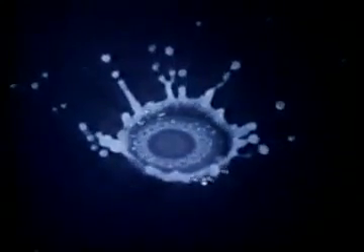For some time, we've talked about phenomena that involve the pressure difference caused by curved interfaces. Here's a beautiful example showing many of these phenomena. A drop of milk that in slow motion will hit a thin layer of water. The drop spreads sideways, and its impingement on the static water sends up a liquid sheet. The rolling up edge of this sheet is unstable and forms a coronet, which is pulled down by surface tension. Part of this liquid moves inwards where it meets to form a spike. The spike in turn is pulled down by surface tension.